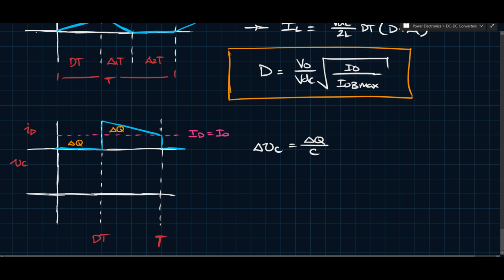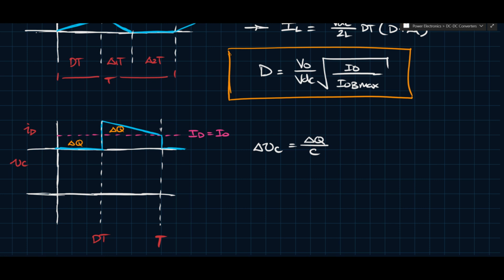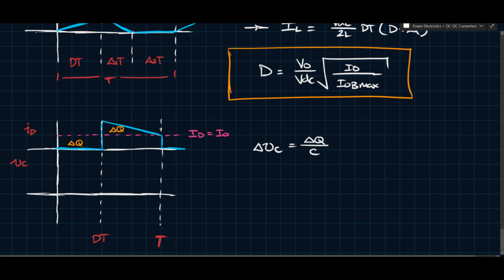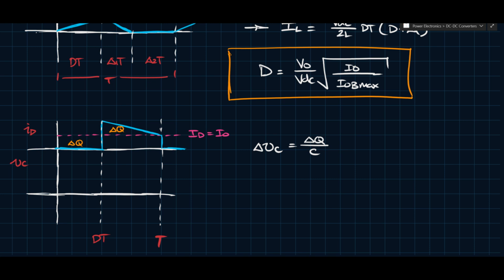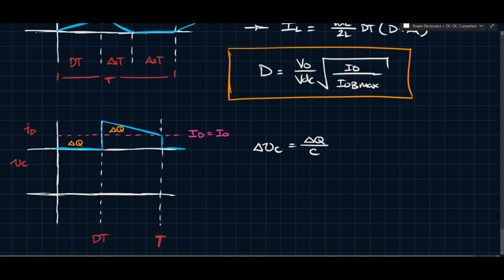That'll be whatever the excess charge is, because overall, the same way that the inductor has volt-second balance, the capacitor has charge balance. It's basically the analogous thing for capacitors, but for the current: the average current has to be 0 over one switching cycle. So what that tells us in this case is that we end up with I/O times dt divided by C, because that's what delta Q is equal to.